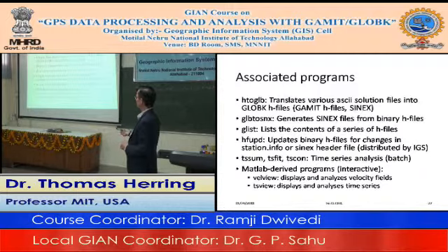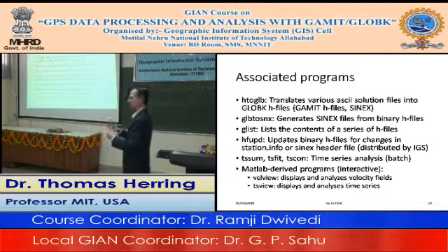TSSum, TSFit, and TSCon are time series analysis programs that are written in batch. TSSum is the program that actually extracts the time series out of an org file and puts them into site-dependent files. It appends to the existing values that are there typically. TSFit is a fitting program that allows you to estimate positions, velocities, annual sines, cosines, post-seismic earthquakes, etc. It will read earthquake files from GLOBK. We often call this a prototyping tool because it allows you to essentially take all the inputs you're going to use for GLOBK.